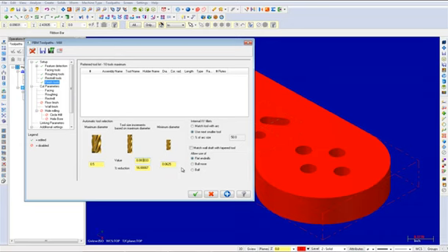I will now explain a few of the parameters found on this page. Internal XY fillets is where you choose a strategy for selecting or creating tools to machine internal fillets in the XY axis. This strategy applies only when the minimum tool diameter is less than or equal to the fillet. Match tool with arc is selecting or creating the tool. Mastercam uses the fillet size plus the stock to leave value you define in the floor finish and wall finish cut parameters.